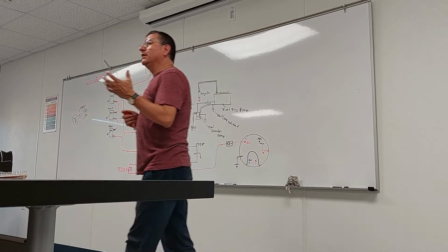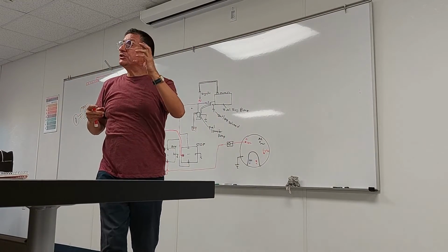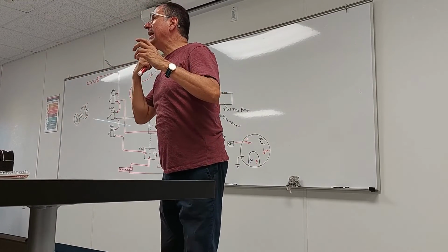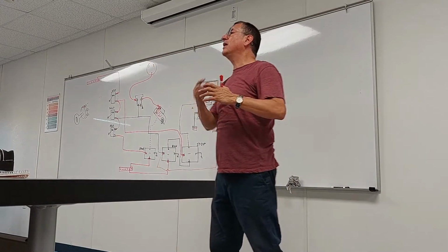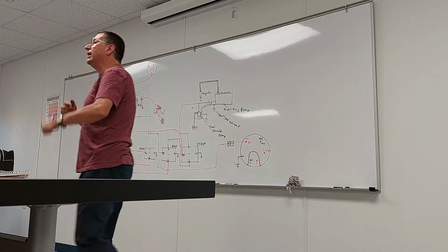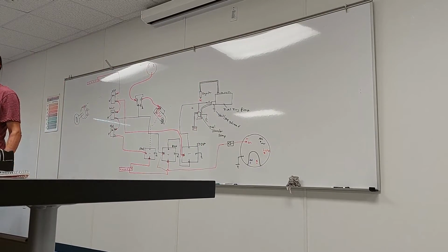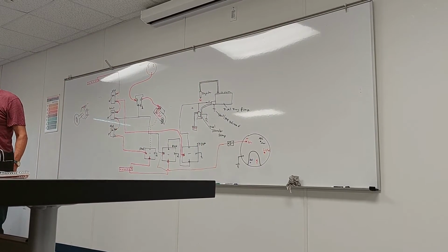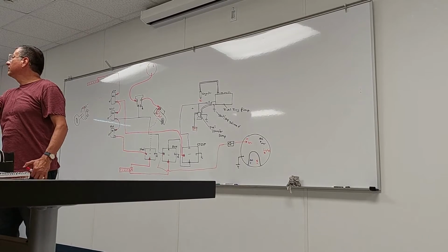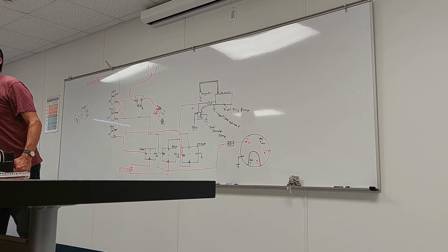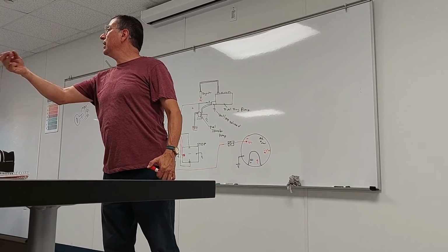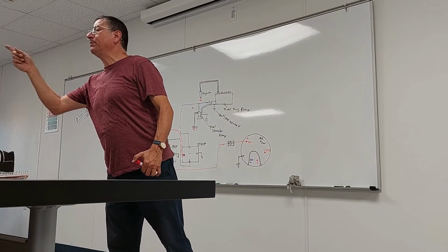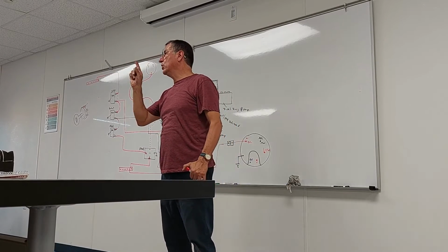In the engine, you have 3 switches used to kill the engine. In any type of marine engine, you have 3 switches to kill the engine. Give me one switch. Oil pressure, exhaust gases temperature, and coolant temperature. Coolant temperature, not raw water, coolant.